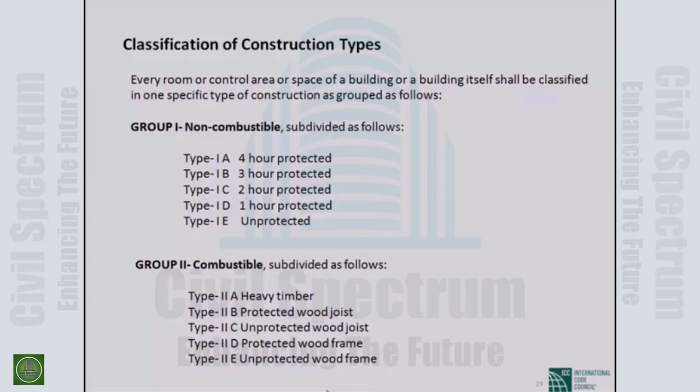Any structure which is steel is normally said to be unprotected, but if you wish, you can make it protected for 1 hour, 2 or 3 hours, as designed. You can coat steel differently, with different types of material from low cost to high cost.